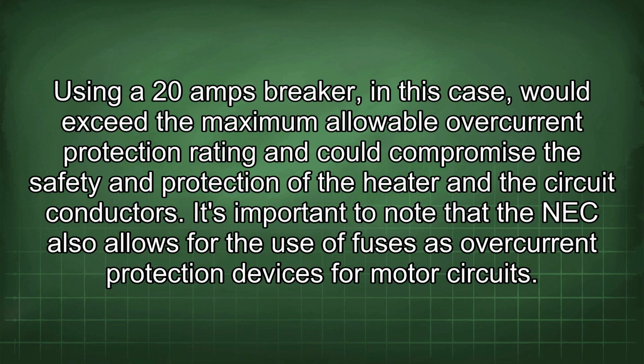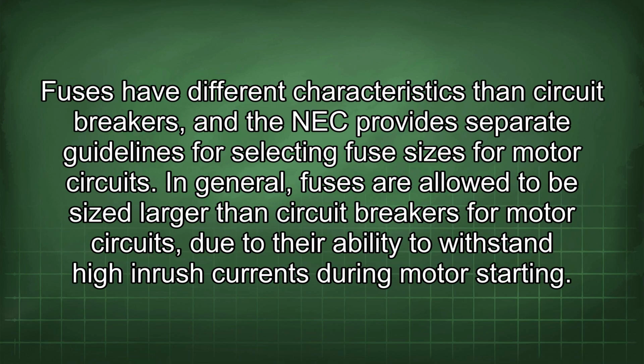It's important to note that the NEC also allows for the use of fuses as overcurrent protection devices for motor circuits. Fuses have different characteristics than circuit breakers, and the NEC provides separate guidelines for selecting fuse sizes for motor circuits. In general, fuses are allowed to be sized larger than circuit breakers for motor circuits, due to their ability to withstand high inrush currents during motor starting.